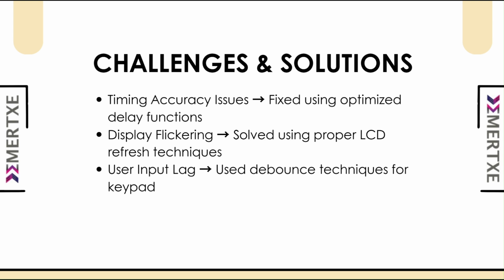We faced challenges and solutions. Timing accuracy issues, where the food was not cooking or getting started properly, were fixed using optimized delay functions. Display flickering was solved using proper LCD refresh techniques, so we can see perfect time and temperature on the board.